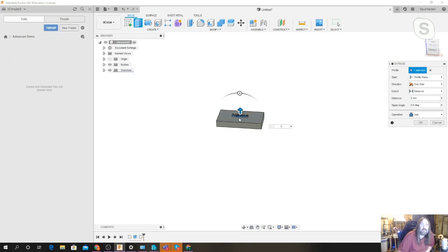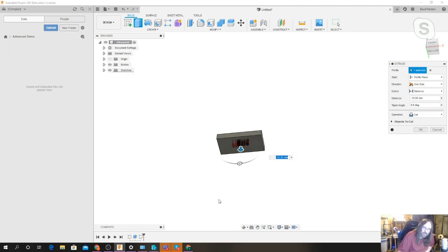Now this is a cool feature. If you wanted the name to cut all the way through the model, you can actually hit extrude. The little arrow shows up. You can zoom it a bit so it's easier to see. You can turn the model, and then you can actually click the bottom of the model, and then that'll pull it right down to the other side, so the opposite wall.